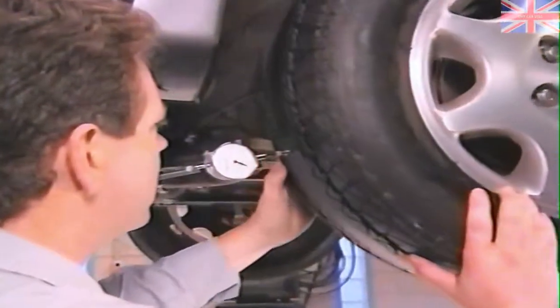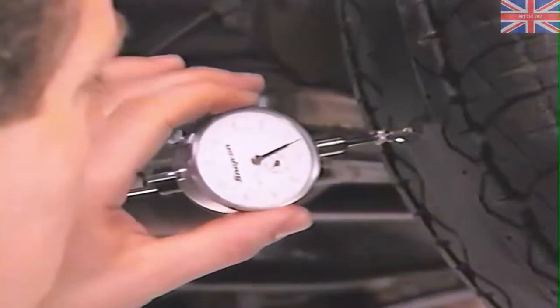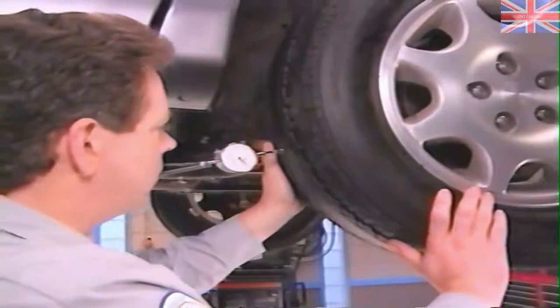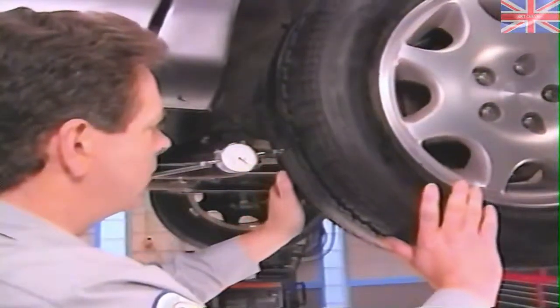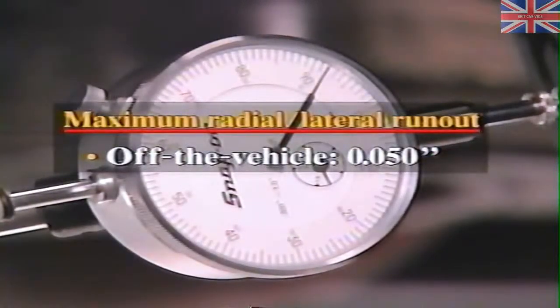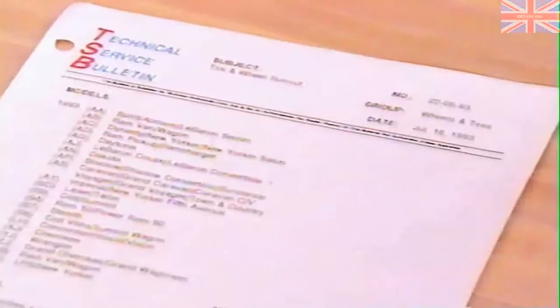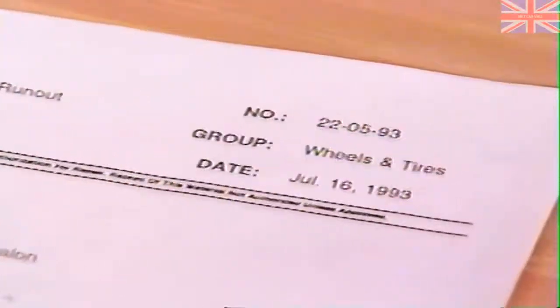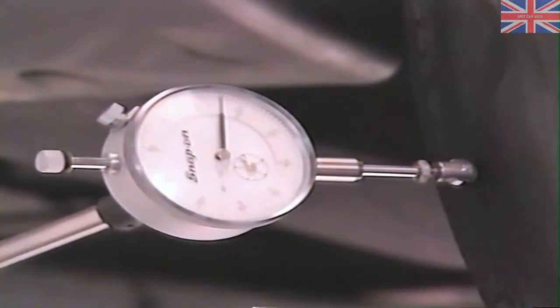We slowly rotate the assembly one complete revolution and zero the dial indicator on the low spot. Then, after rotating the assembly one more complete revolution, we note the total amount of runout indicated. In this case, radial runout is excessive. As a general rule, the maximum allowable assembly radial and lateral runout is 50 thousandths of an inch when measured off the vehicle and 60 thousandths of an inch when measured on the vehicle. For exact tolerances, refer to TSB 22-05-93. The lateral runout is within specifications.